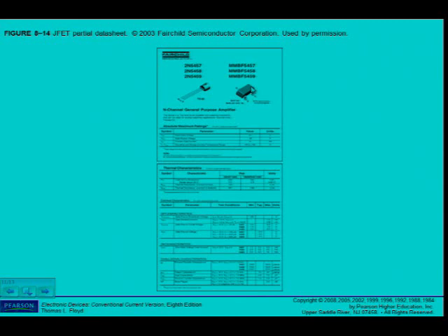Alright. For those specific devices, you'll have to make sure which device you are working with. A bit lower, underneath the on characteristics, there's IDSS for the three different devices, and they give me a minimum, a typical and a maximum value. Can you remember in the example they said typical value?